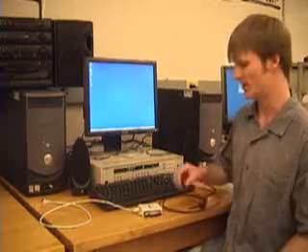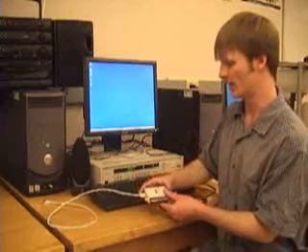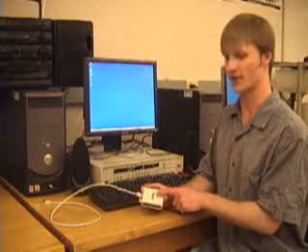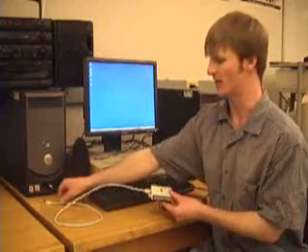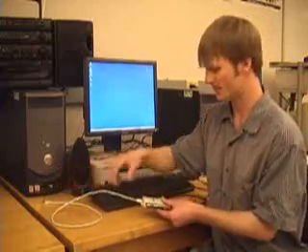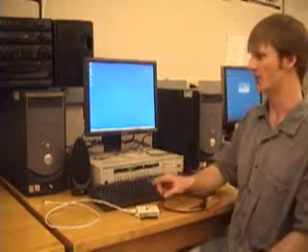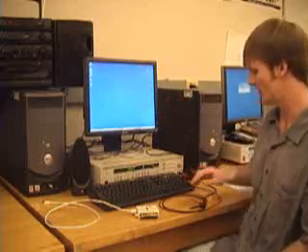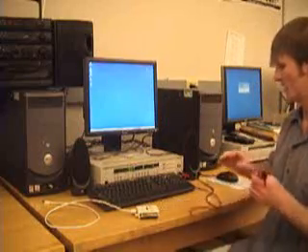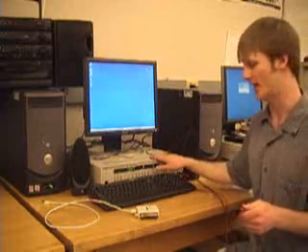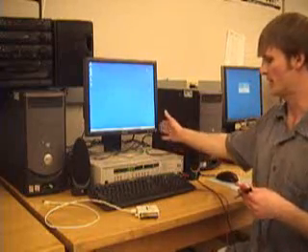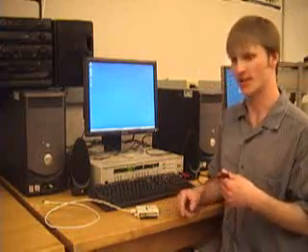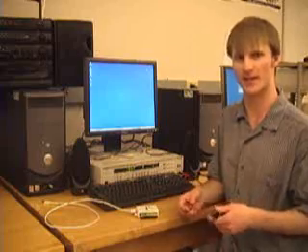The purpose of this lab is to learn how to set up a data acquisition card. This is an external data acquisition card from National Instruments that connects to the computer using a USB connection. We will acquire that signal using National Instruments software LabVIEW, and we will be acquiring a function generator signal, and we will use LabVIEW to control the data acquisition card and change the sampling rate to determine the effects of aliasing.